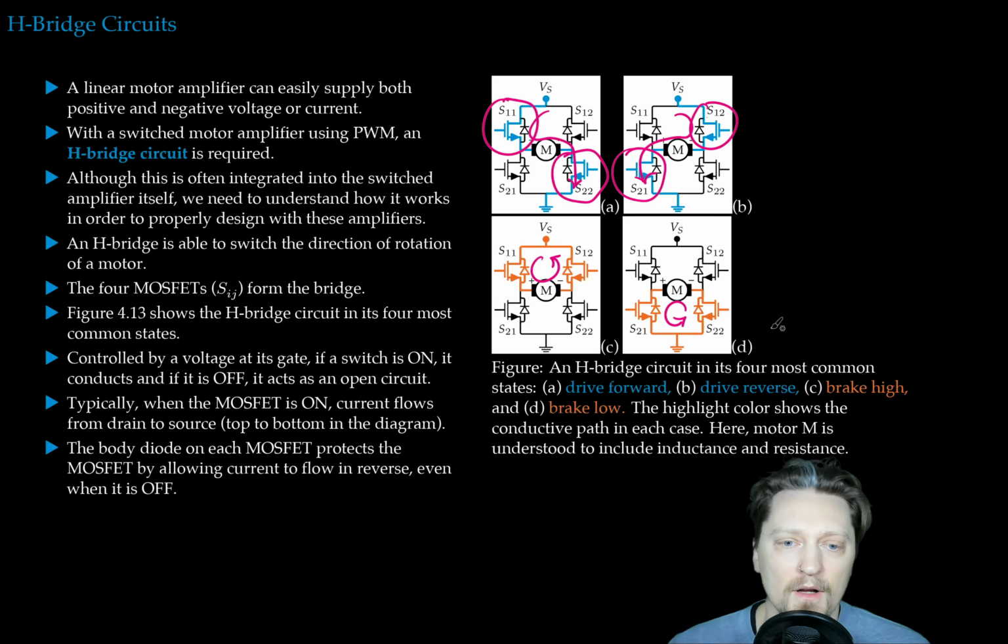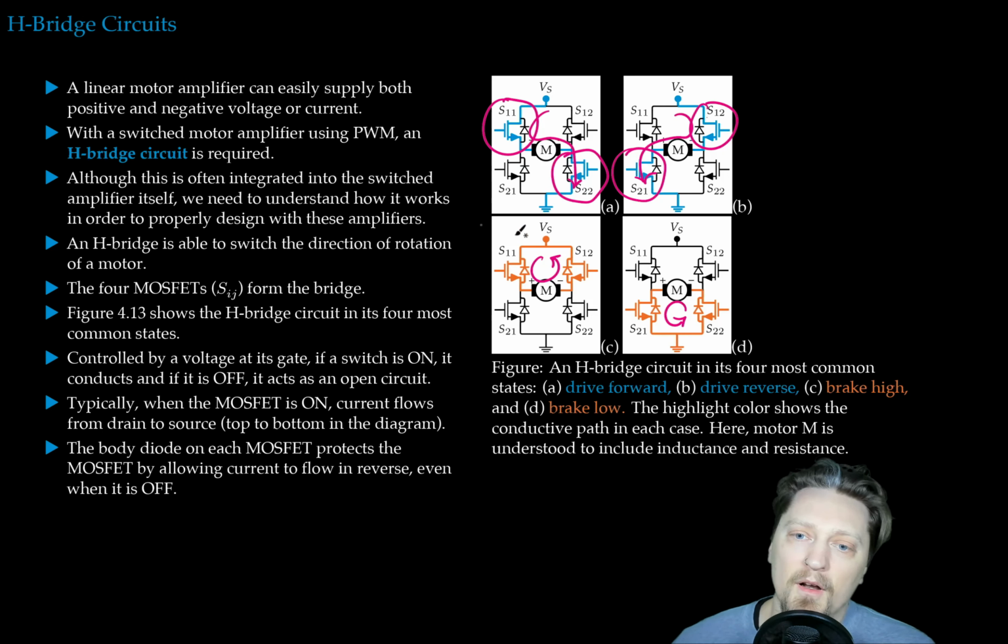These two states are called brake states because there will be current flowing around, so there will be resistive heating and therefore energy dissipation from the system. There will also be mechanical energy losses because there will be bearing damping on the mechanical side. So these are called brake states, where we allow current to flow and we allow the mechanical system to dissipate energy.